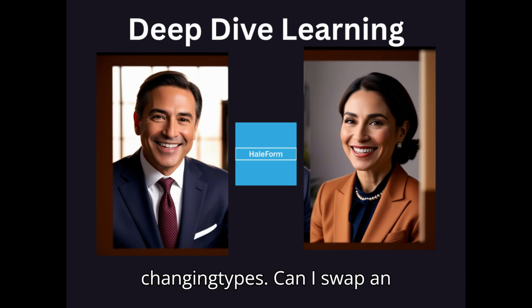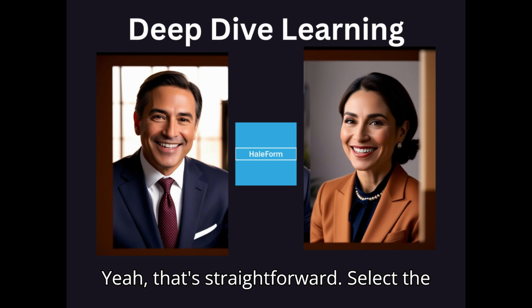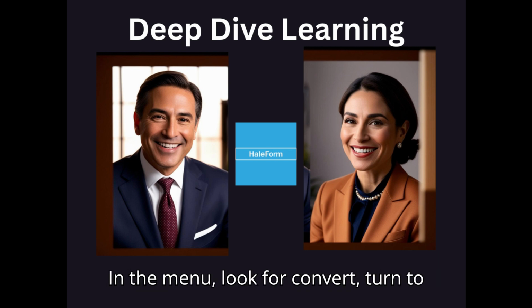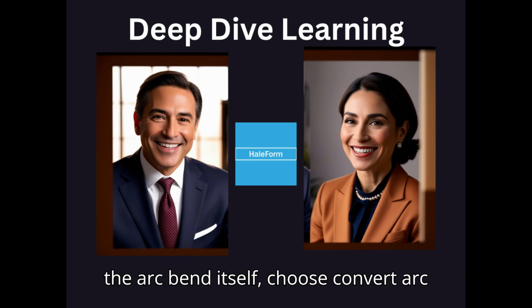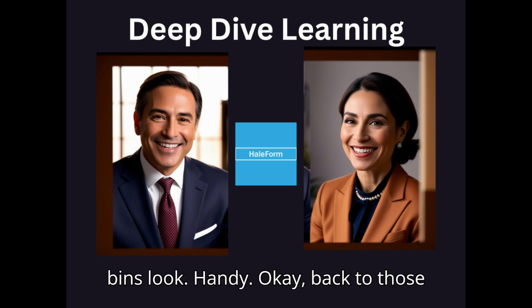What about changing bend types? Can I swap an elbow for a smooth arc bend or vice versa? Yeah, that's straightforward. Select the elbow, the turn feature, right-click it. In the menu, look for Convert Turn to Arc. Click that. To go back, right-click the arc bend itself. Choose Convert Arc to Turn. Gives you flexibility in how bends look. Handy.